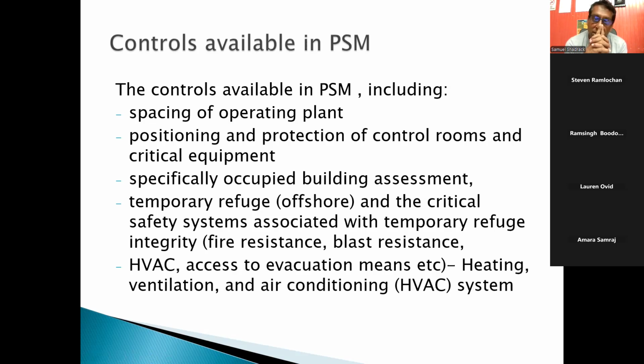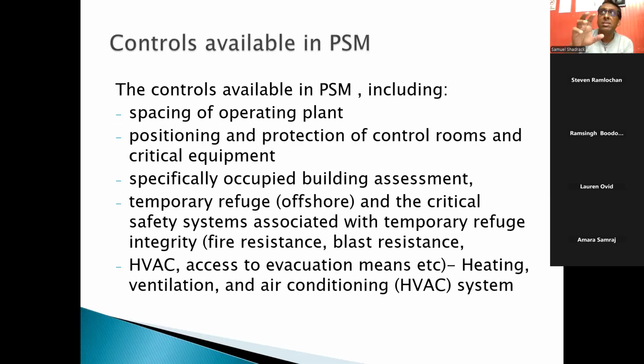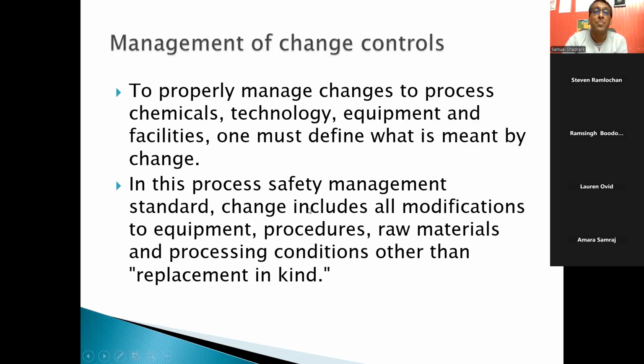Let me say that again: these are not just words. The safety of a refuge room can be judged by a formula, like stability over integrity, and you get a figure like 20 minutes. So a refuge room, which is designed to withstand a fire or explosion, would have a certain figure. That's what all of these calculations are about. We could stick to something meaningful: the refuge room has stability and integrity for 30 minutes. Meaning, in the 30 minutes that you're there, you should be rescued, because a refuge room is not meant to live in on an offshore platform. It's meant for you to go there to get rescued.